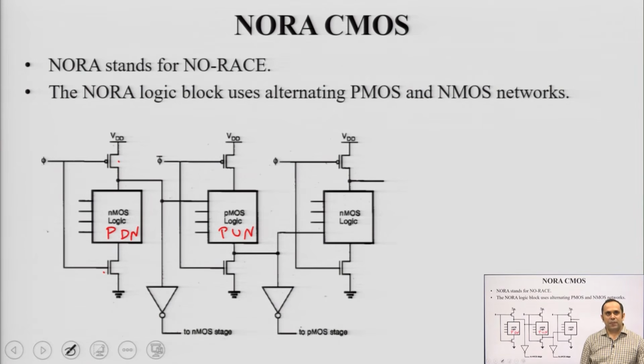This is still a standard dynamic sequential circuit only. Just to understand how it works, let us just say that phi here, the clock here, is 0. In that case, this output, if I call it node 1, pre-charges itself to VDD. So, the first stage here is in pre-charge stage. This is one here. So, this PMOS is off, but this is one here. So, this is on. This is discharging here.